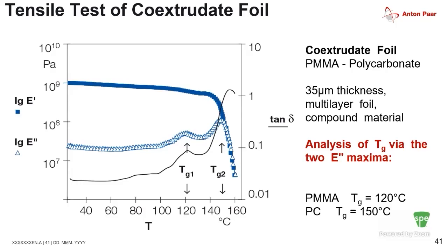I see two distinct glass transition temperature points. Whereas if they are miscible in each other, you would have a single point, and it would shift one way or the other depending on which has higher precedence for your material. And so,